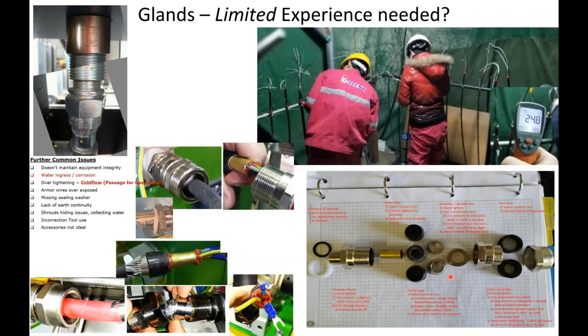And like you mentioned, the majority of the failures come down to the glanding, okay? Which nobody is really taking care about because it's just a piece of the art. And if there is a $100,000 worth installation, the glanding itself is barely €5 or $5. Okay, so it's not something which people really pay attention to.